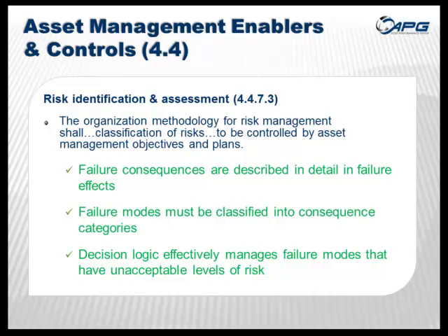Also, failure modes, when classified and described effectively and in detail, will provide significant information about the events that occur during a particular failure, and hence help us again to understand those risks beyond just the categorization. Lastly, the decision logic that's applied in an RCM analysis on a failure mode by failure mode basis puts a very heavy emphasis on the requirement to manage unacceptable levels of risk where the failure can result in injury, death, or damage to the environment. And therefore, in order to manage risks at an unacceptable level, it should in most cases become quantified. We need to know what is acceptable, hence we are classifying, understanding and managing the risk associated with those failures.